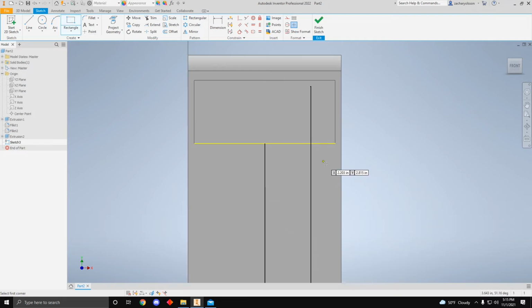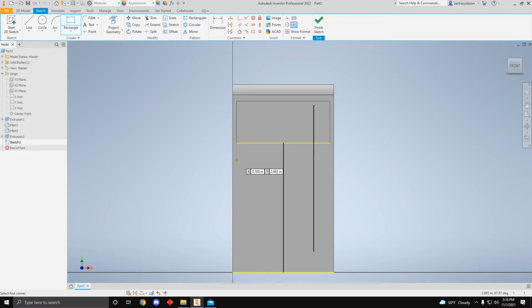So now we're just going to make our boxes, and if we go somewhere here, we're just going to make the boxes first, and then we will adjust them to our size needs later. So we're going to make these 3 boxes, anywhere really, just somewhat close to make it move less, and there we go. Now we have our regular boxes. We want them all to be the same size and the same distance apart though. So like we've seen, we go to dimension, and we make this dimension, let's say 0.5. And now it's 0.5 tall, but we want it to be a square.